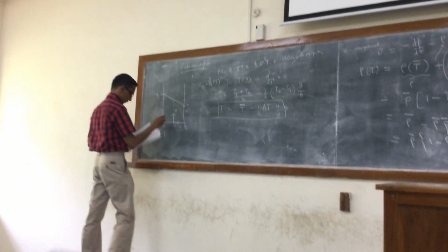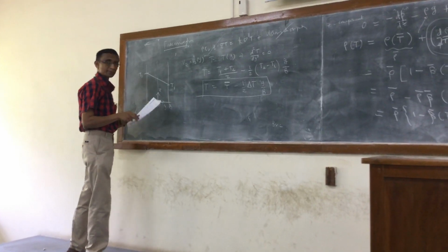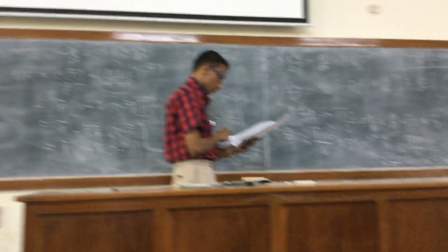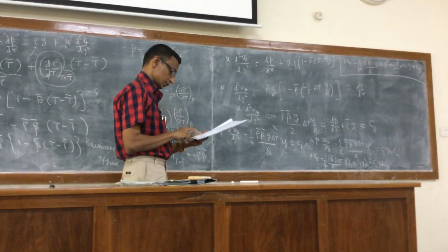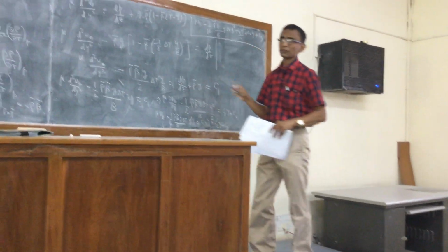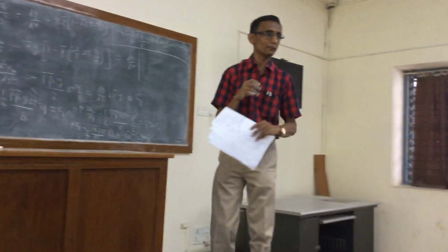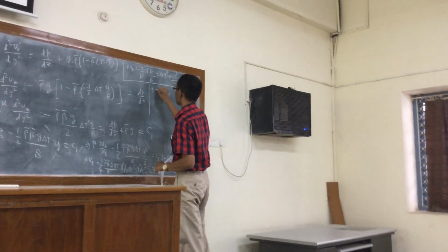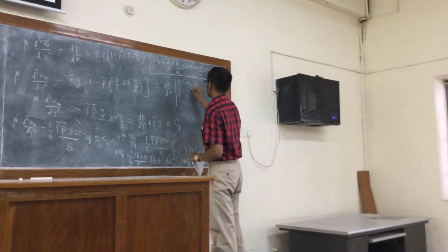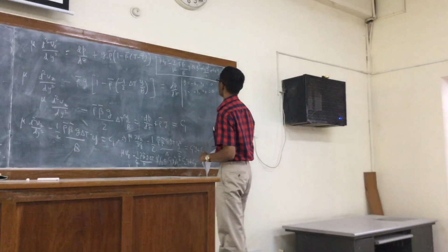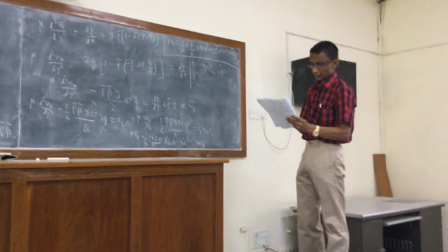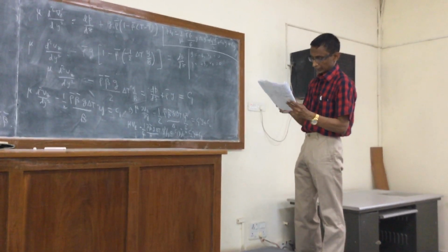The boundary conditions are clearly the no-slip boundary conditions that can be applied. I guess that's what they're doing, right? That again is a question. When you're dealing with gases, whether that's really valid or not, but we apply that. So y equal to minus b, dz equal to 0, and y equal to plus b, dz again is equal to 0. Two of the constants can be determined.